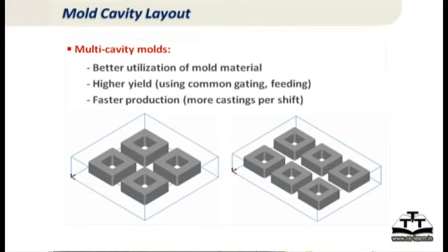Apart from that, what can happen is variation in molding, where proper ramming is not there. If it is high pressure molding, then it is much more consistent. Yes. But if you go to manual operation, the weight consistency suffers. So here we are looking at multi-cavity molds, and remember, by default it's good, if you have a small casting and generally a big mold, to put more cavities in the mold, so you are utilizing the sand better.